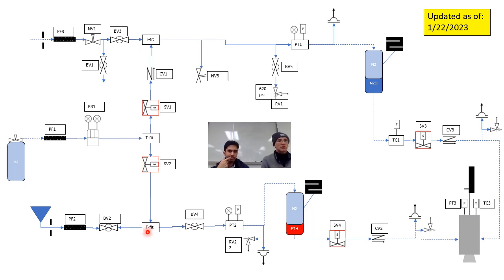After we verify that the valves are working correctly, we're verifying that instruments are working properly. So we want to make sure, we know the temperature should be about 20 degrees Celsius. Are the thermocouples reading 20 degrees Celsius? Are the pressure gauges and pressure transducers reporting into the LabJack and into LabVIEW, into our GUI, that it's atmospheric pressure when everything is vented at atmosphere? So basic checks like that.